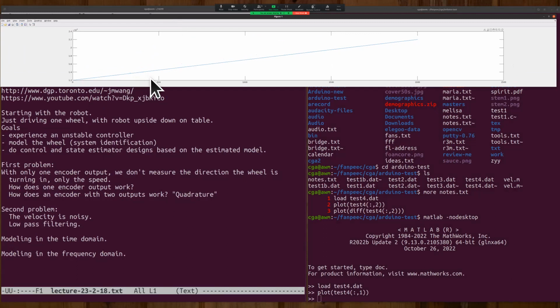It's a signal that increments every time the servo runs. And the point of that is if there are any kind of spikes in this thing, it means the timing of the servo is not working. I'm actually running the servo 200 times a second, every 5 milliseconds. Okay, so that seemingly works.